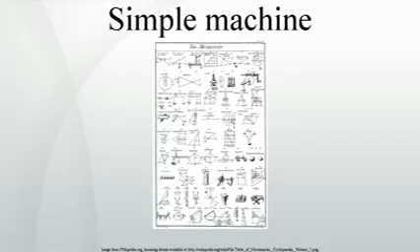Kinematic chains. Simple machines are elementary examples of kinematic chains that are used to model mechanical systems ranging from the steam engine to robot manipulators. The bearings that form the fulcrum of a lever and that allow the wheel and axle and pulleys to rotate are examples of a kinematic pair called a hinge joint. Similarly, the flat surface of an inclined plane and wedge are examples of the kinematic pair called a sliding joint. The screw is usually identified as its own kinematic pair called a helical joint. Two levers, or cranks, are combined into a planar 4-bar linkage by attaching a link that connects the output of one crank to the input of another. Additional links can be attached to form a 6-bar linkage or in series to form a robot.